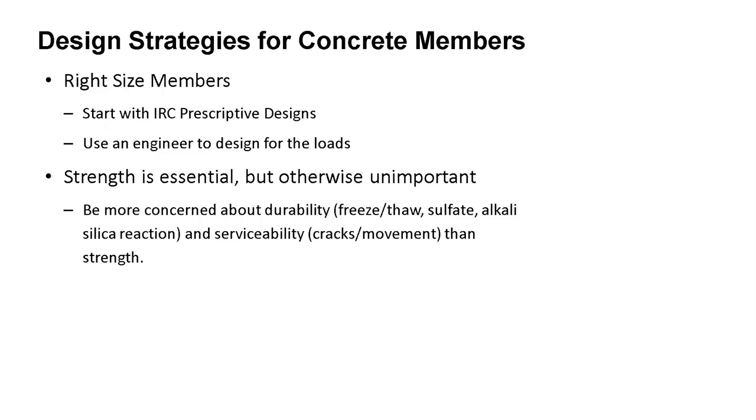Right sizing members I think is important. And I like this quote I heard from another engineer: strength is essential, but otherwise unimportant. A lot of people are really caught up in the strength of the concrete that they deliver and provide. And honestly, as a structural engineer, I don't care a whole lot about the strength. I care a whole lot more about the durability, which in part is a function of strength, depending on what we're talking about. But I care about durability and serviceability, the life of the concrete and how will it perform over time.